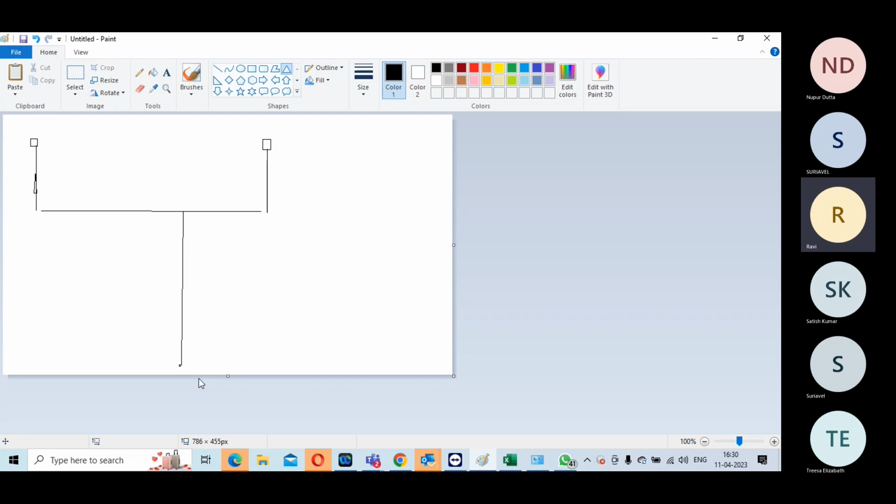Generated clock is more for a timing information point of view. But from a clock insertion point of view, the source clock, everything will start from here. You can have a buffer over here, mux, output of the mux. Here you may have defined a generated clock. But the balance has to be seen from this point only. You'll start building the clock tree over here, generated clock, then you can build this route separately if you want. Or you build everything together.